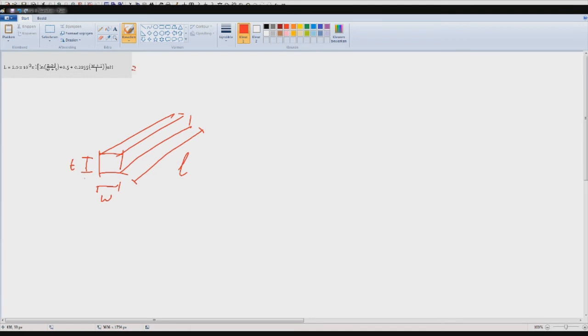And if we fill this in as L to be 10 centimeters, you might think that's very small, but you saw how small the time constant was and how fast the projectile is done accelerating, so no need for long rails. And you will see that too long rails will actually destroy your railgun.